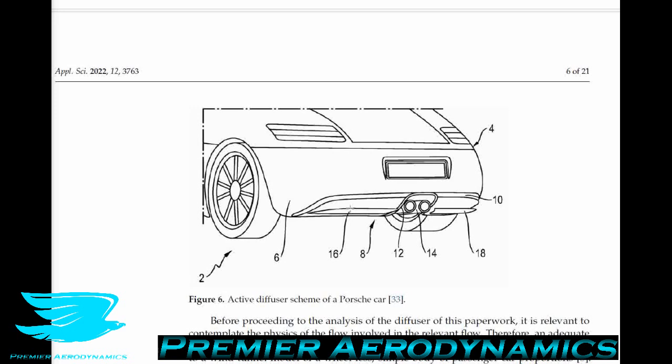That is the diffuser. And the reason why this part is so important is because it can make the car's underbody act very much like an expanding cross-sectional area. So if the car is quite low to the ground, or if the car features skirts on its sides, so this is like when you have these little panels coming down to the ground, this prevents air from escaping from the underbody and prevents external air from entering. Then the volume of the air under the car is effectively isolated from the surroundings.